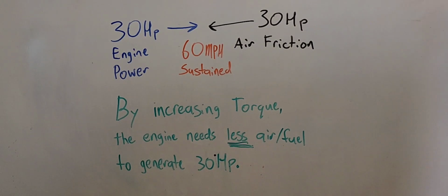And we do that when you look at our torque times RPM divided by 5252. Now, because our RPM hasn't changed, our torque will go up. So naturally, if we need to make less power, as we've demonstrated with power as airflow, we simply have to reduce the airflow by reducing the throttle opening percentage.